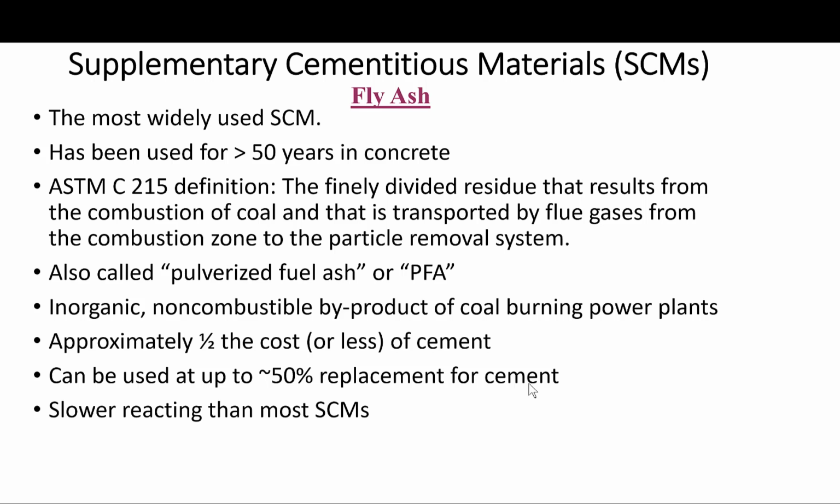Okay, so that's the message you have to remember about fly ash. Of course, in your case, as a customer of a ready mix supplier, just make sure you read and understand the mill certificates for the fly ash being used, that they comply with your job specifications, and that you are able to flag any inconsistencies or non-compliances of the materials we just talked about, such as containing sulfides or anything of that nature.